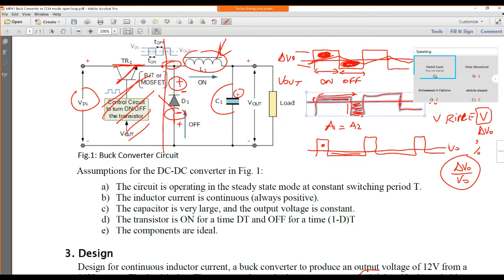Now, first of all, once you need to design, and I'm talking practical wise, not theoretical wise, if you need to design your circuit, first of all, you have to define your switching frequency to be used, and after that, your controller to be used and so on. So the first thing to be defined is the switching frequency, because everything will depend on that.